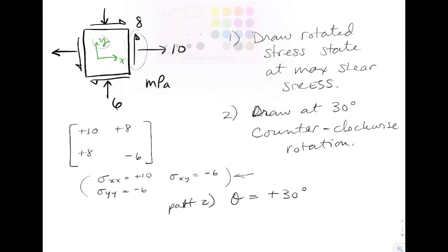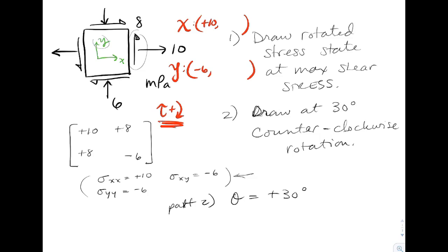So we need our initial points here. So the Mohr circle canvas requires these 2 points started off. And just remembering when I draw the axes in just a minute, tau is clockwise positive. So on the x face, we've got 10 in tension. On the y face, 6 in compression. We have a shear stress on the positive x face that would be causing the element to rotate counterclockwise. So we'd end up with a negative 8 and here with 8. So we're going to remember these.